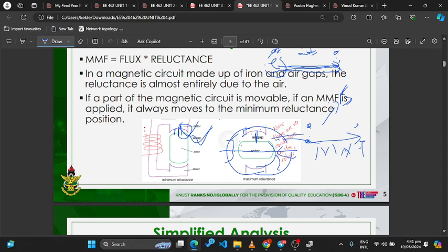Now that this pole over here is enjoying least reluctance, there will be a point in time where this pole, if this is pole A, this will be A prime. This is its pair. Then there will be another time where this will be turned off. This pole over here will not be excited, and these two poles will be excited. Then least reluctance here doesn't make sense, because this is already off.